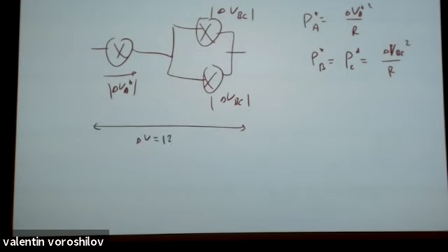Because total voltage is 120 volts, this will be equal to 2/3 of 120, which is what? 80. And this is equal to 1/3 of 120, which is 40.